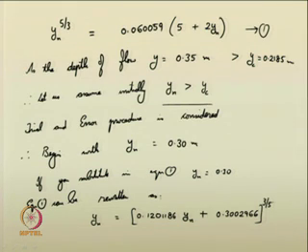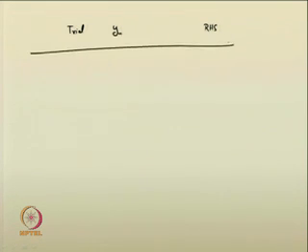So, on the left hand side there is one y n existing, and on the right hand side there is another nonlinear term of y n existing there. You have to match both of them in the trial and error procedure. So, this is trial y n and this is the RHS y n. If I start in the first case with 0.300 as a trial value of y n, you are getting your RHS as 0.5200.